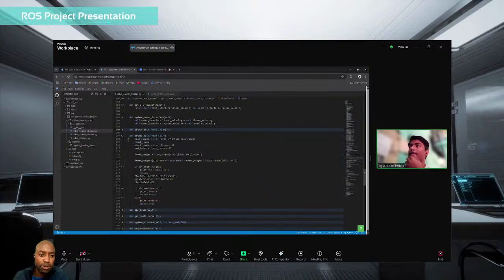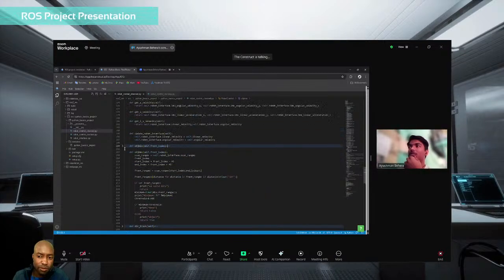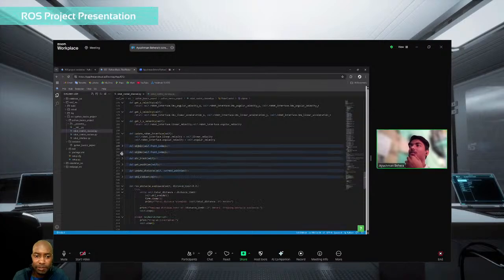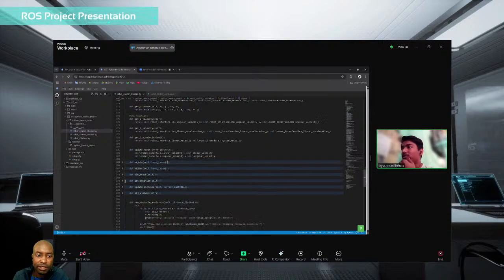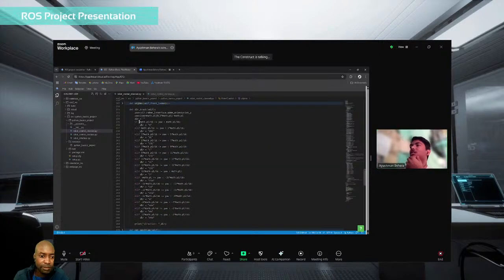All right. You also spoke about having challenges with the dictionary. Can you talk us through what those challenges were exactly? Yeah, as in dictionary, I think the function was the distance tracker. In the distance tracker, we have to get the odometry orientation, like which direction to go, because the other two directions are kind of useless to us right now in a 2D plane. By getting the yaw value, we are essentially getting the direction it is facing.